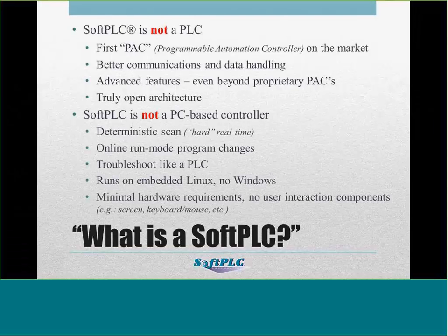The other thing about Soft PLC is it's not a PC-based controller. It does not run on Windows. We don't have a screen or a keyboard or a mouse. We run on very small footprint type hardware with no moving parts, no hard drives, and it runs like a controller. So it's deterministic. You can do run mode program changes.